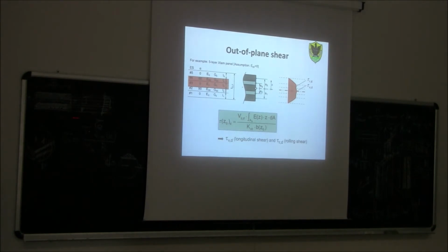For 5 layers, we have a slightly different trend, so we have to keep in mind that this time we have 3 resisting layers. So parabolic distribution, first layer, then constant because it is the non-resisting layer. Then the third one, we have another parabolic distribution, but as you can see here, the value is much lower. Why is it much lower? Because here we are much closer to the neutral axis, so the variation is very little. Then again constant, and then again parabolic.